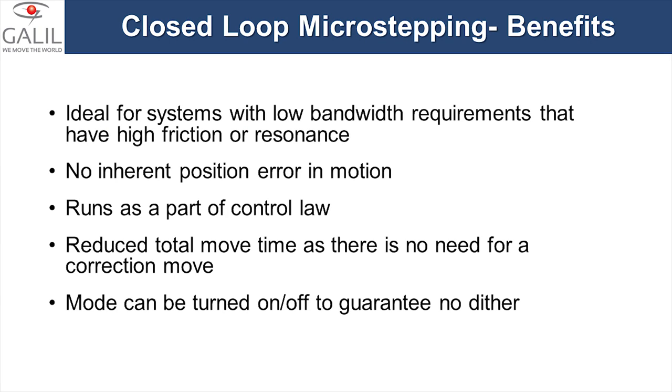Because we're still driving the motor as a stepper, this mode is ideal for systems that do not require fast responsiveness to position error while in motion. As the motor moves, the controller will continuously account for any position error and adjust the commanded reference position accordingly. The user does not have to command anything besides moving the motor.